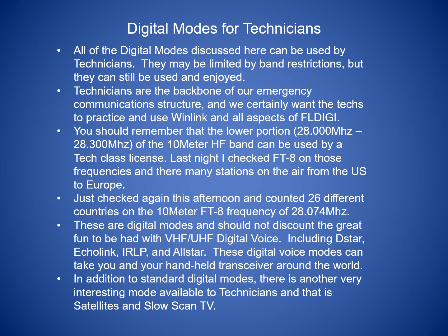You should also remember, though, that on the 10-meter band in HF from 28 megahertz to 28.3 megahertz, you can use the FT8 and FT4, and also a little bit higher you can use voice. But the FT8 and FT4 and the other digital modes can all be used on HF in the lower portion of the band.